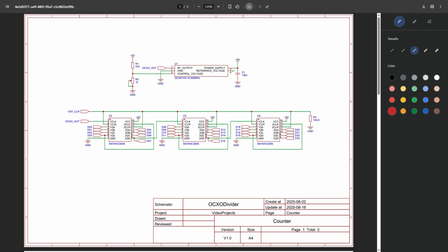Pin 3 is the VCO input. The resistor network that this pin is connected to is a variable voltage divider. Current flows through R1 and R2, creating a voltage drop on each one, as Ohm's law tells us. What we need to do is find the right values of R1 and R2 so that the VCO voltage falls in the range of what the datasheet told us, 0 volts and 4 volts.